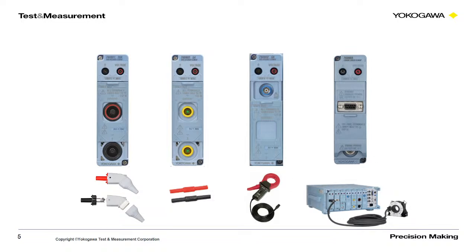This one, it takes a current, say 1,000 amps, and it has a turns ratio, we'll say 1,000 to 1, and that would turn that current into 1 amp. So the power analyzer is only seeing 1 amp. So this element supplies power to that CT and then reads the current directly.